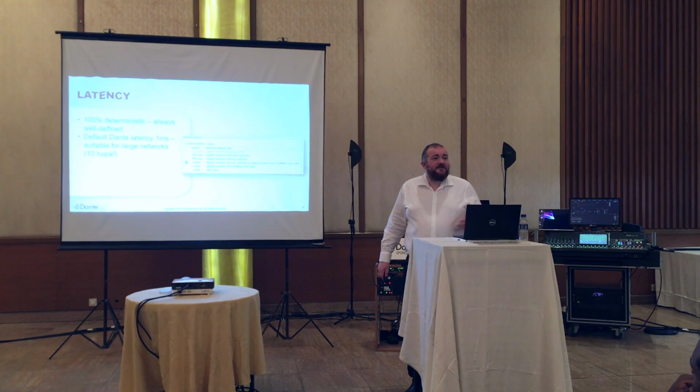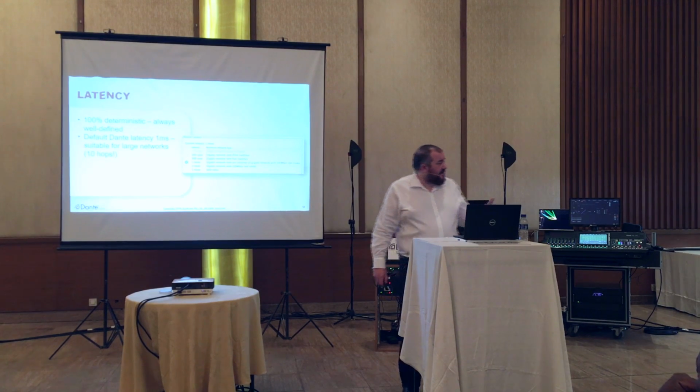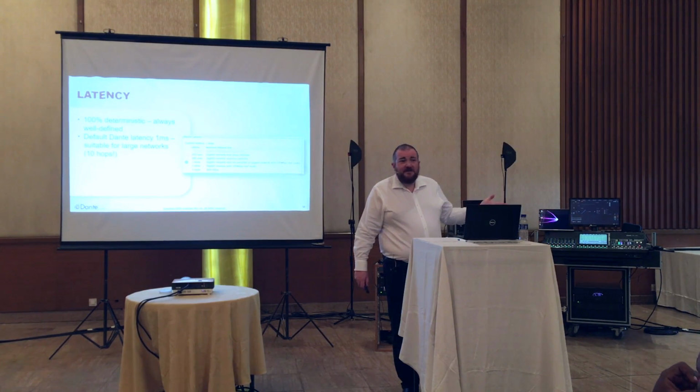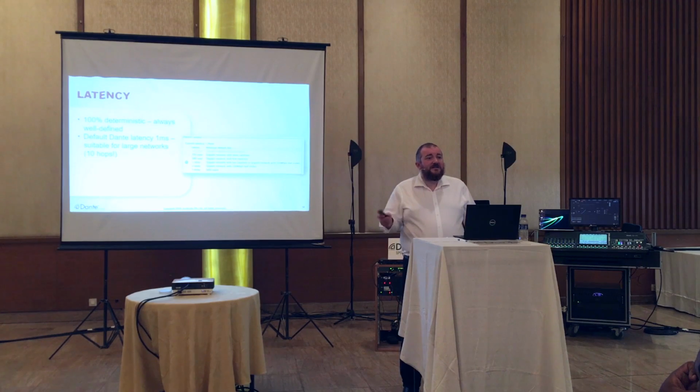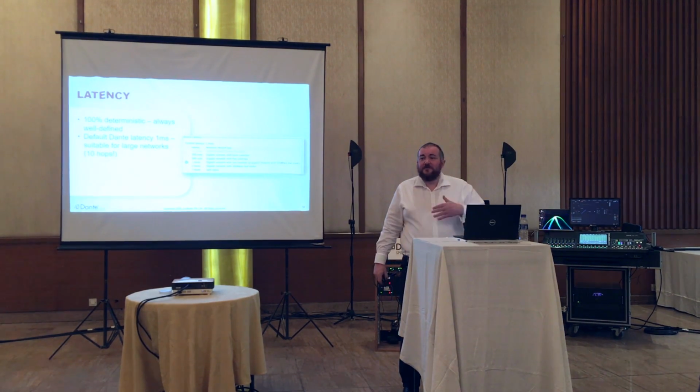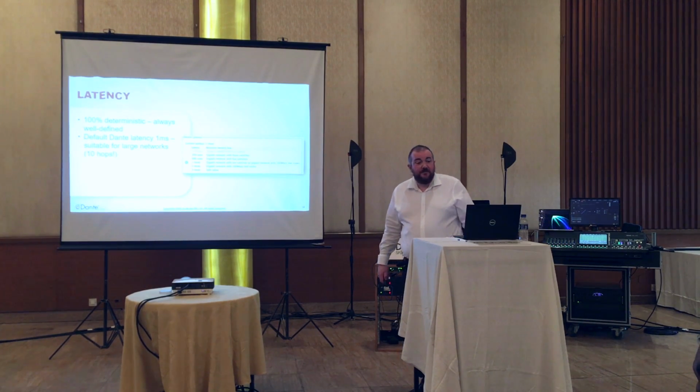And that's a much better measurement. It's kind of the difference between taking a system controller for a loudspeaker system and dialing in the meters delay versus getting your analyzer out and actually taking an impulse response and dealing with what the real delay is in the system. It's always going to be a better result if you measured it. And that's why we've included the latency monitor.